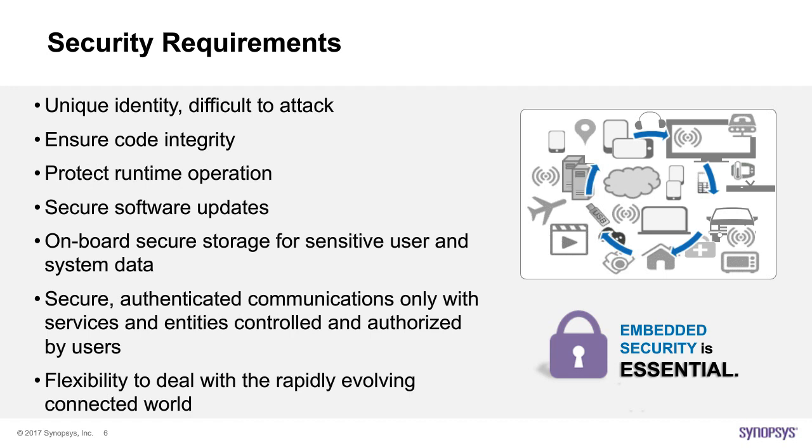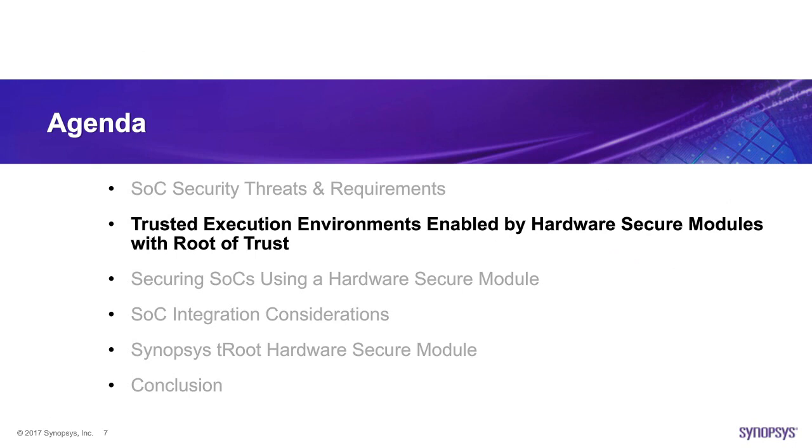So, in order to secure an SoC at different phases of operation, you need to be able to run your security functions in a secure enclave that is protected from the non-secure areas of the SoC. This is called a trusted execution environment, and I'll discuss how a hardware secure module can provide one implementation of it.